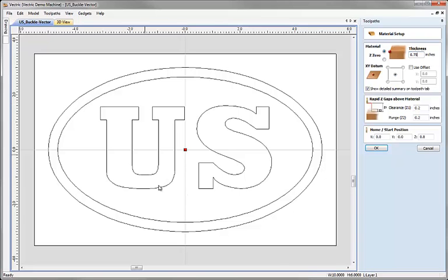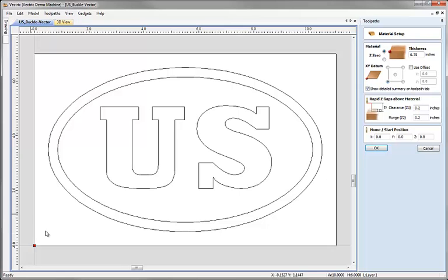And now you remember that we did our drawing for this with the datum set in the middle. This is often quite a nice way to do it because you can make sure things like the ovals are centered on 0, 0. Now I'm coming to machine this. My preference is actually to machine with the datum in the lower left hand corner. So I'm going to click on that and move the datum down to the lower left hand corner. That means where that red square is now shown is going to be 0, 0. X0, Y0 is going to be here, and everything I toolpath and then cut on my machine will be referenced from that point.